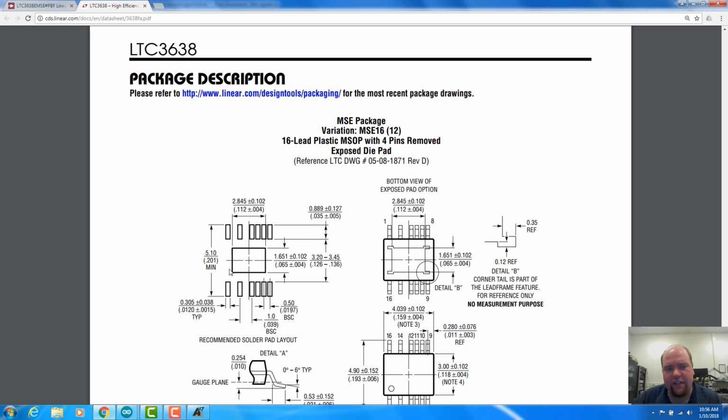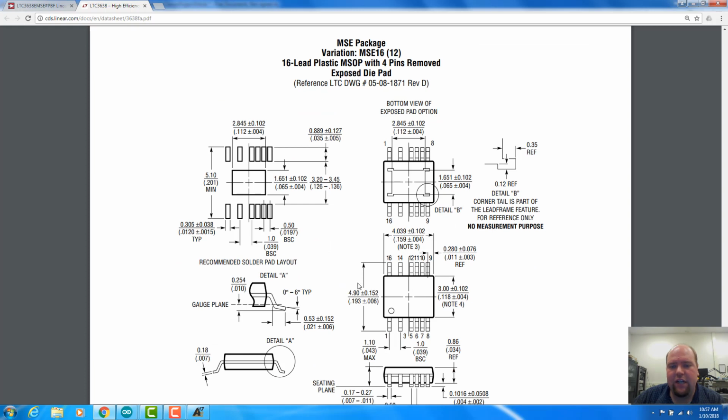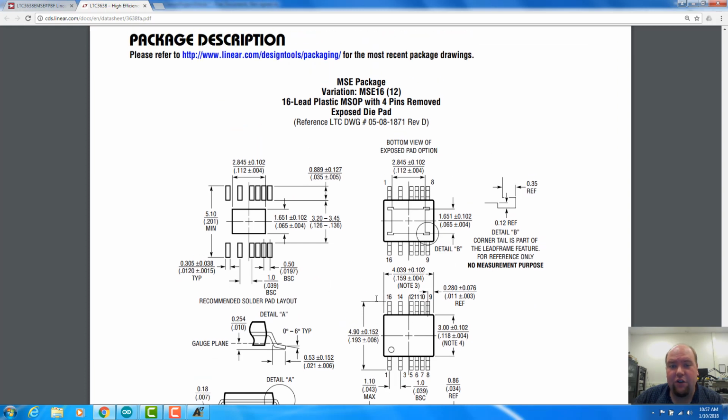We also know the length of these pads is given here. It's 0.889 millimeters, plus or minus 0.127. Clearly, this part was designed using imperial units, so it's really about 0.4 inches max. Sometimes, whenever we have these tolerances, we have a size and then a plus or minus. Especially when it comes to defining the physical geometry of the part, I usually like to use the larger size.